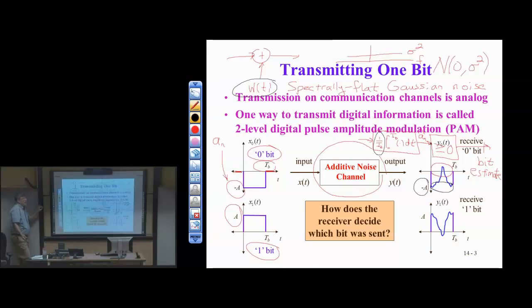I'm low-pass filtering. We looked at the integrator before in homework. It has a low-pass character. If we're careful, we can make it a low-pass filter. And here we're being careful because I'm only integrating over a finite amount of time. I can't have the output grow without bound. I don't have to worry about BIBO stability because I'm using this integrator over a finite length of time.